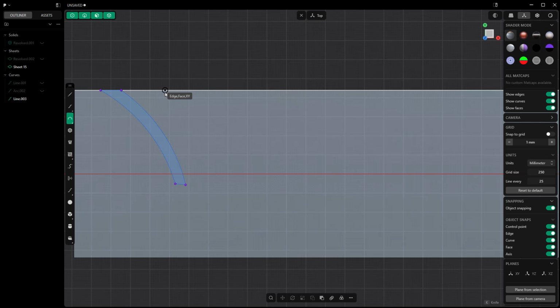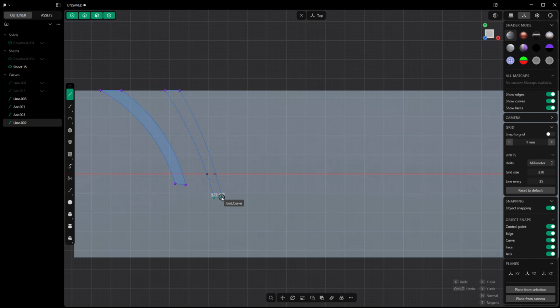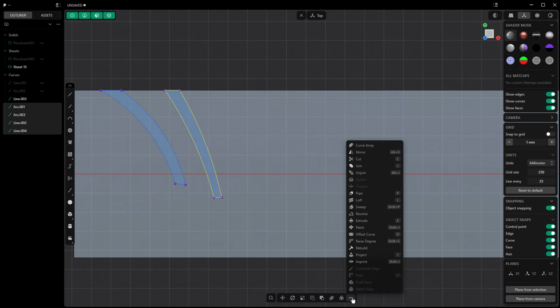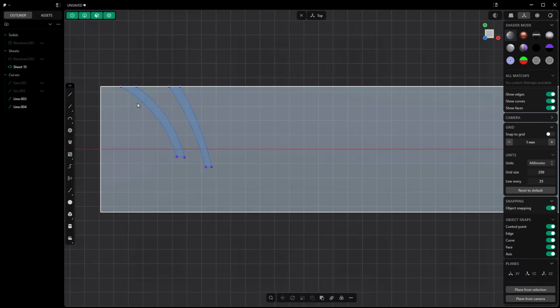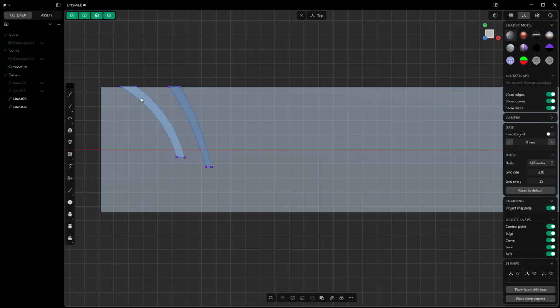It's going to go a bit further. So maybe cut over here. And we'll repeat that. Again, Shift and R will allow you to repeat if you want to use the shortcuts. And then our line tool, right click, line tool, right click. And then we want to select all of these and join them together. All right, so those are two tread, I guess, blocks or patterns.